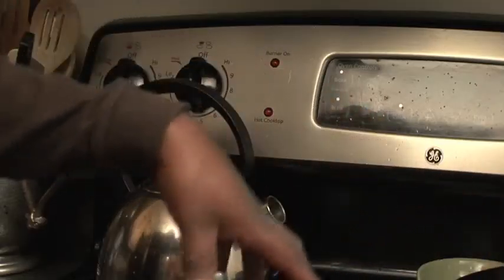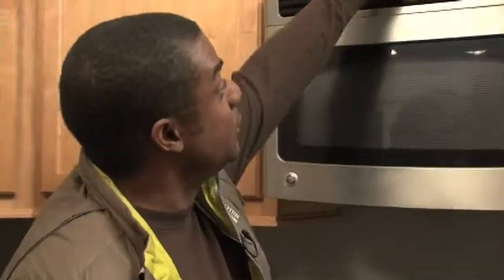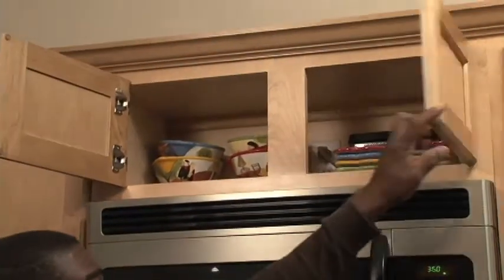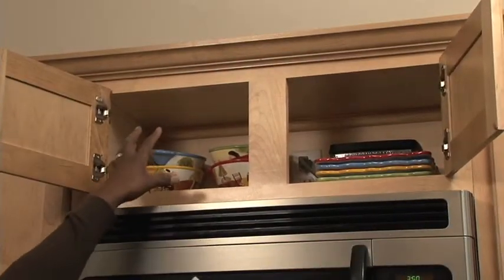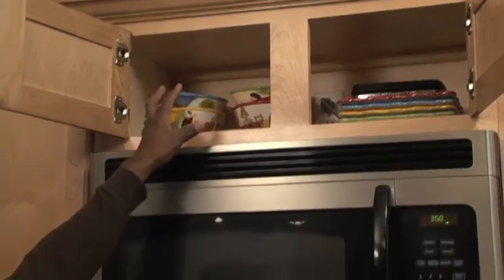We only want to recommend that they switch to gas if the kitchen exhaust vents to the outside. How do we know if it vents to the outside? We take a look above the vent hood to see, and in this case, we don't have any ducting going to the outside. So for this particular homeowner, gas is an option because it is here in the house, but we only recommend a switch to gas if they're also willing to add venting to the outside and use it while they're using their gas stove and oven.